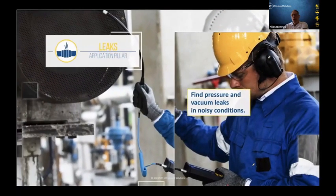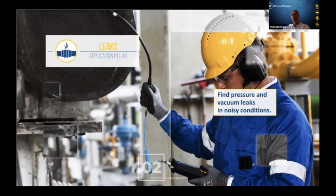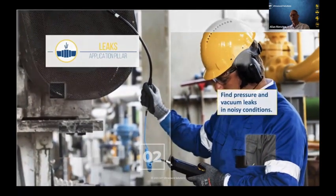Well, let's talk about applications now. So we understand how ultrasound works and why ultrasound is advantageous for us. What we need to do is understand where we can use it. And the first application pillar that we talk about is leak detection. Pretty much everything will leak, whether it's compressed air, SF6 gas, or vacuum leaks. There's all kinds of areas where our plant will leak.